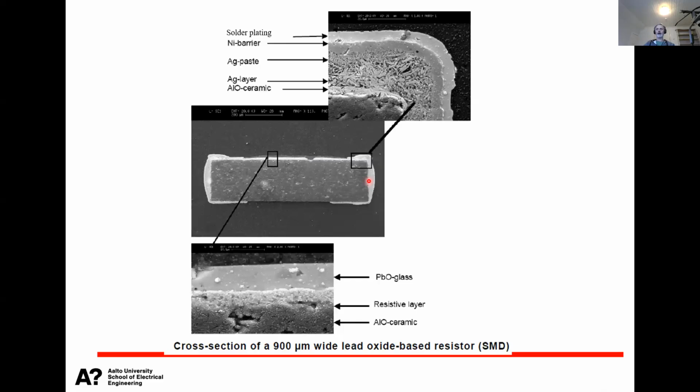First you have a lower resistance, and then you start burning the resistive material off with the laser. So you decrease the cross section of that material, so you increase the resistance, and when you have achieved the target value, you just stop it. So basically, I hope you understood.